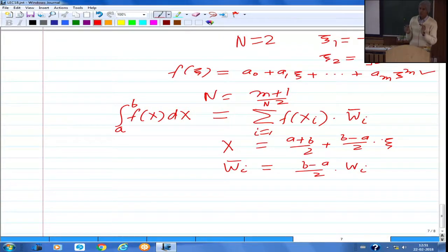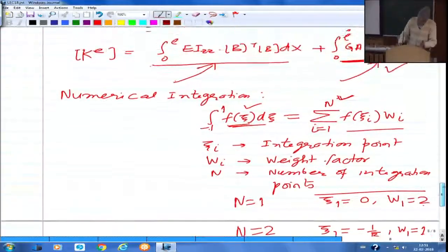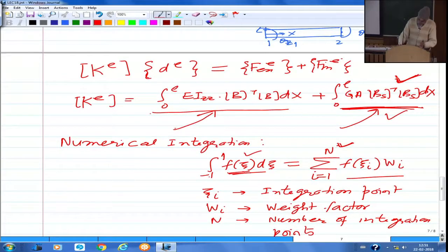So if you want to exactly integrate that numerically, the highest power is 2, that is your small m, so (2 plus 1)/2, 1.5, essentially approximated to 2. If you want to actually integrate this energy, the stiffness contribution from transverse shear energy, you need to use capital N equal to 2. So you will get two values, x1, x2 with corresponding w1 bar, w2 bar, evaluate the whole of the matrices, multiply them and sum over those 2 points, and you will finally get the exact value.